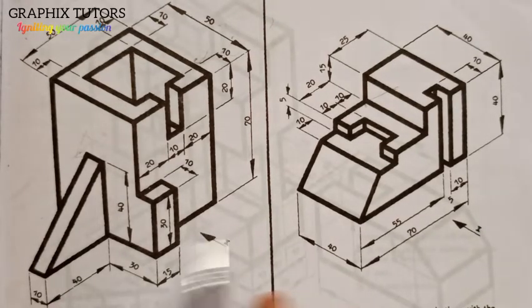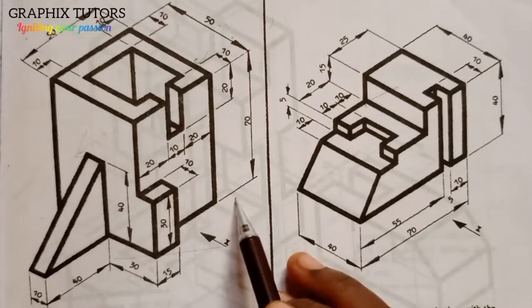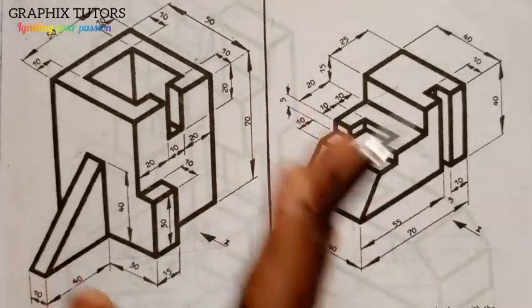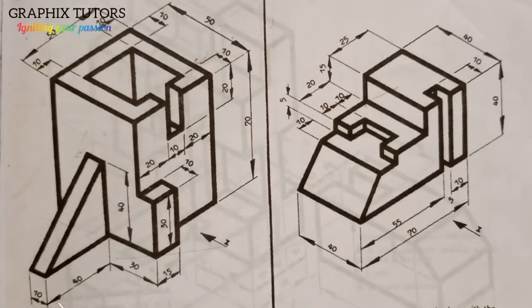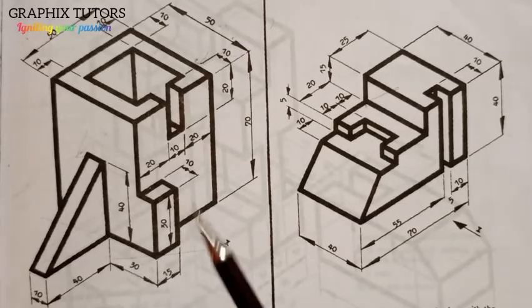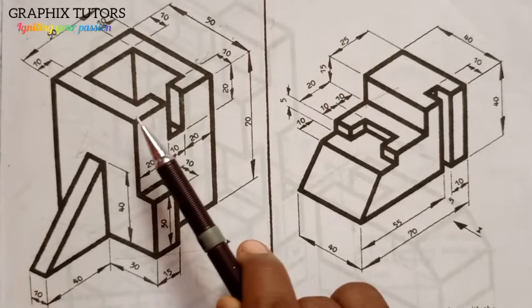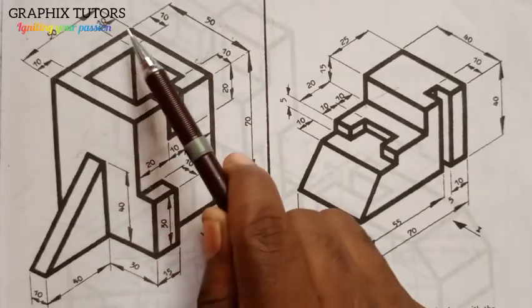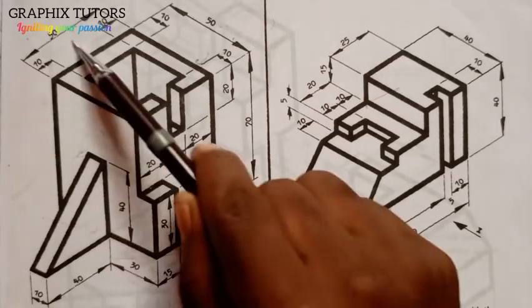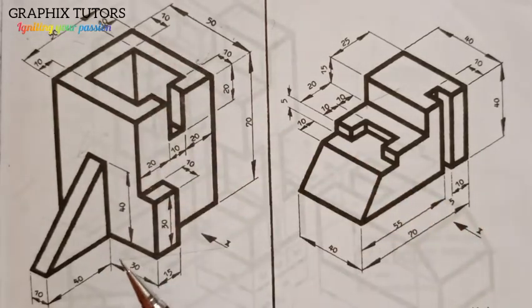Now if you look at this very well, you're going to discover that this is the x-axis here, because if I put in my inclined axis this way, everything here is x, this is z, and this is y. If you look at everything facing this side, looking from this direction, from here to here is 40, right? And if you trace it from here to here, they're all parallel, and that is 50. So the x like this is 40 plus 50, and that is 90. So I'm going to draw 90 millimeter.